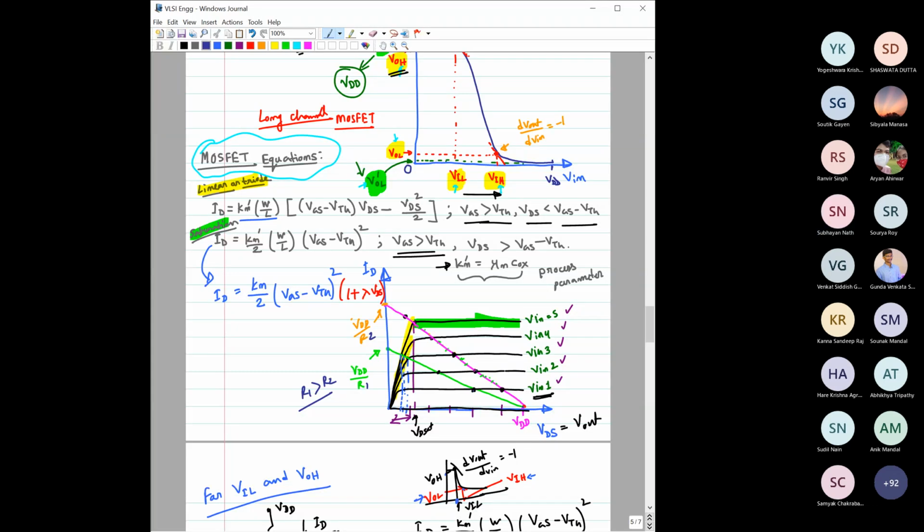So will W increase if gain increases and Kn increases? Yes. Then, I think you are on the right path, then the drop of voltage will also increase faster. So V out is equal to VDD minus ID R, and in ID there is Kn, so if Kn R is higher, the drop would be faster.